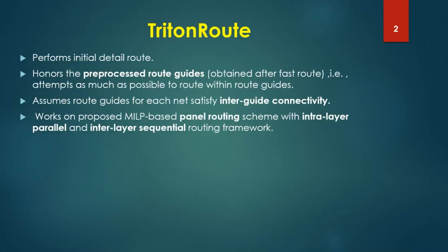Now that the detailed route has the route guides, it has to find the best possible way to make the routing connections between the different points. For that, it uses MILP based panel routing. I will be explaining all these bold letters which you see on the screen. MILP is actually an algorithm, which stands for Mixed Integer Linear Programming. I won't be going deep into this because it is another point of discussion.